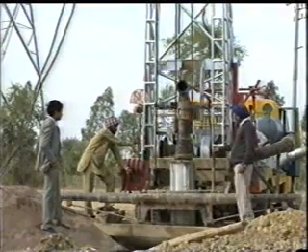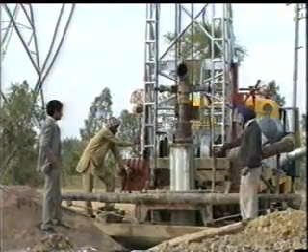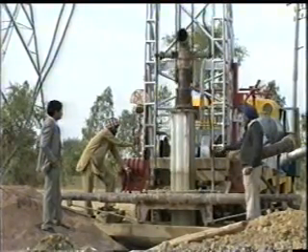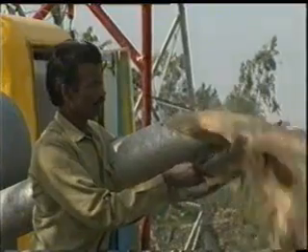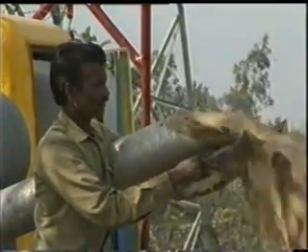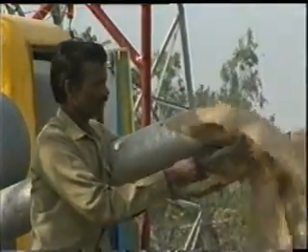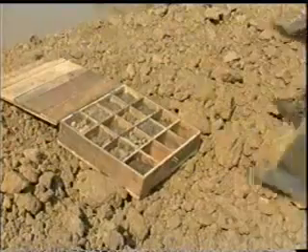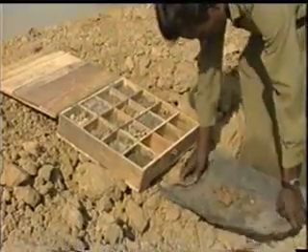For constructing a well, a vertical hole is made with suitable drilling machinery at a hydrogeologically potential location depending upon the geological formation, depth, and expected discharge of the well. Various formation samples collected during drilling are examined for determining the characteristics of an aquifer.